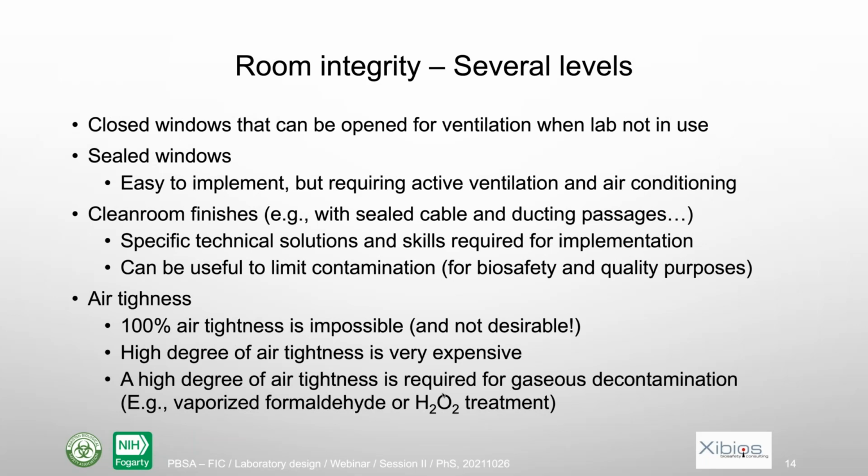And then you can have another level, which is what we call clean room finishes. That means that most things are sealed, like sealed cable, duct, and so on, passages. And also you have finishes that are very easy to clean and disinfect and so on. So that's already a more sophisticated technical solution. And for that, you need specific skills to build that kind of facility. However, it's interesting not just for biosafety, but also to strongly limit contamination for biosafety and quality purpose together, I would say.